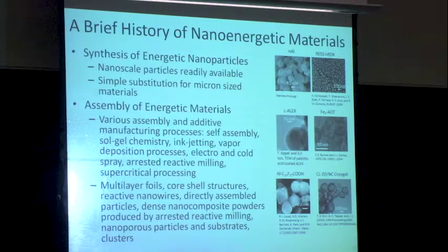So he thought, well, if I take these coated nanoparticles of iron and add very small quantities to my fuel, I can control the temperature at which the ligand, this oleic acid, comes off of the iron particle. Suppose that comes off at a temperature just below the temperature at which I start to make the carbon deposit. Then the oxygen in the fuel line will preferentially react with the iron particle versus the fuel, and I'll minimize the amount of carbon being formed. So it's a different way of looking at how these particles can be used.